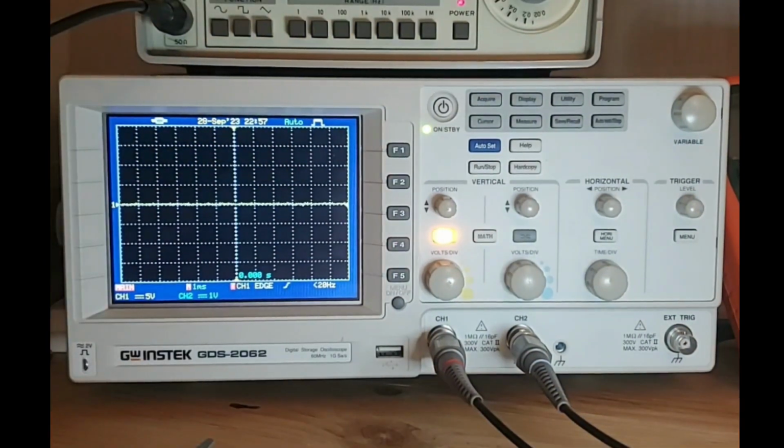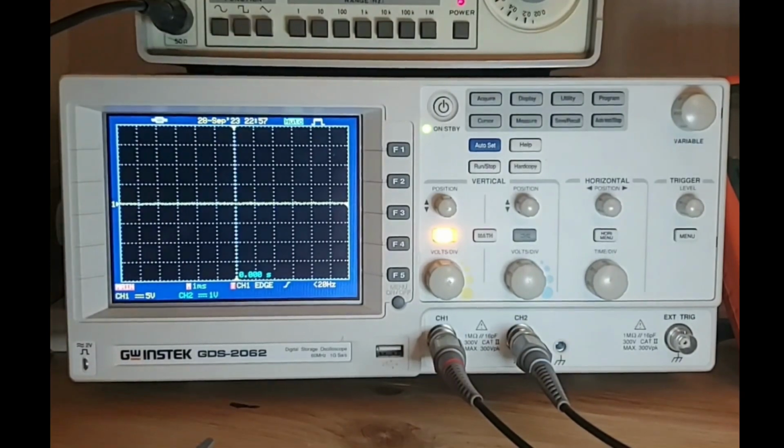Sometimes we want to test if the probe of the oscilloscope is working properly. And to test the probe, the oscilloscope provides us with this waveform, the test waveform, which is shown over here. It says that it is a square wave with 2 volts peak. And you can use this test point to check if the probe is working properly.